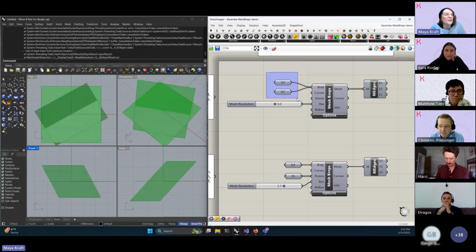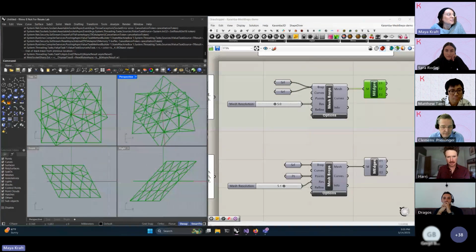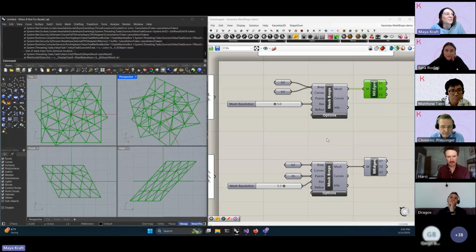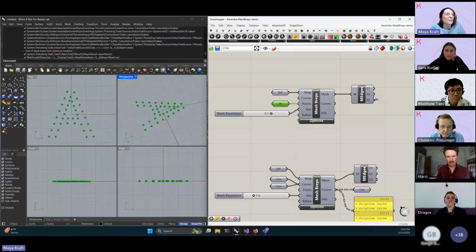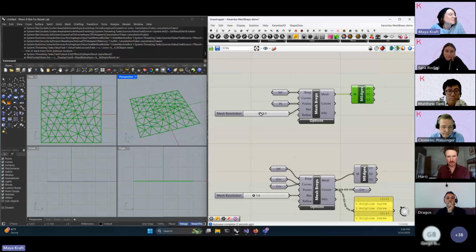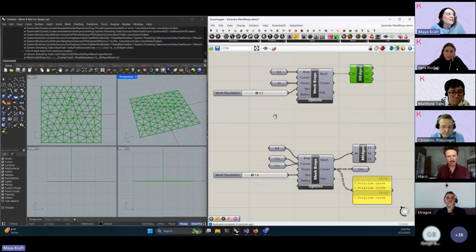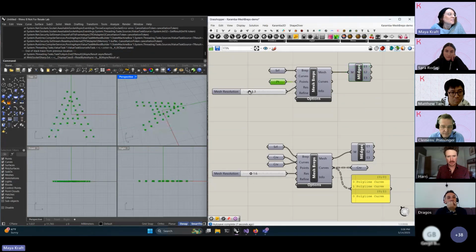The 2 BREPs come in, 2 meshes come out, but they are aware of each other. They will, for example, share an intersection, share edges, share vertices when possible. You can specify a set of points as the input, and these points will show up as vertices in the final mesh. Notice that there's no connection between these points. These are just a cloud of vertices.